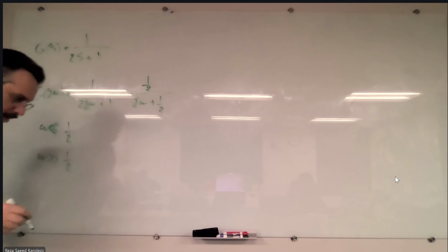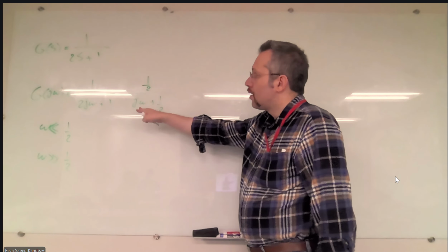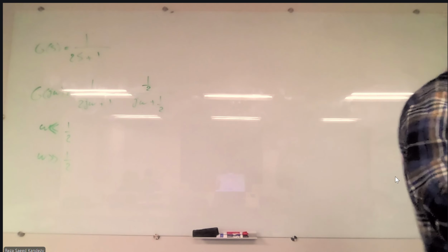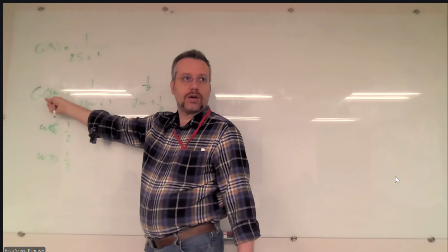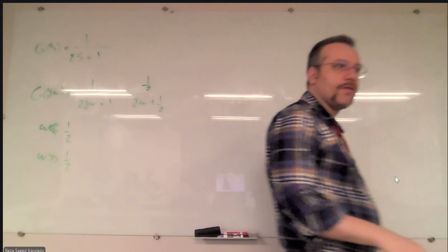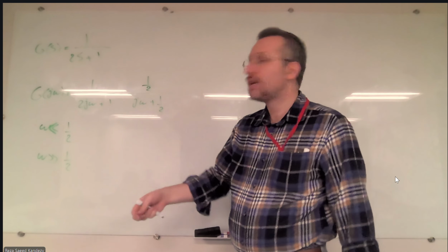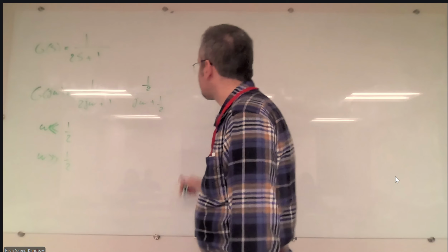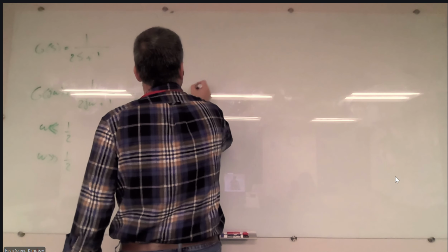Okay, now we wanted to see what's going to happen in our situation. We have two types of Bode plot. One was for the magnitude of the vector that represents our j omega, and another one was for the phase of that. So we wanted to see the behavior of both magnitude and phase for the vector that represents our transfer function. So basically, this is going to be some vector with an amplitude and phase.